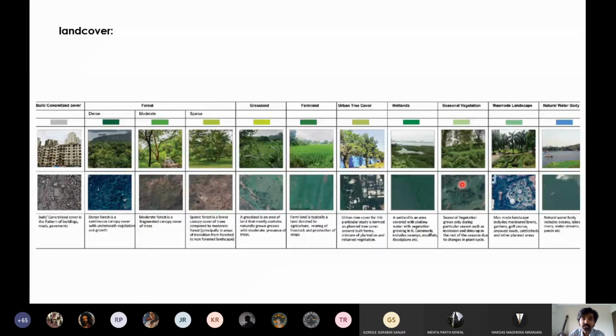And then which are those areas which are under seasonal vegetation? Now, if the site is remote and you've been given this project in May and you have to give your design by July, you only have 2 months. How do you understand what the seasonal variabilities are? One very easy way is to look at the aerial mapping from different times. Let's say Google Earth, for example. When you see that same spot in summers and you see, oh, this is completely brown, then it's very easy for us to figure out which areas are under seasonal vegetation and which areas are under perennial vegetation.